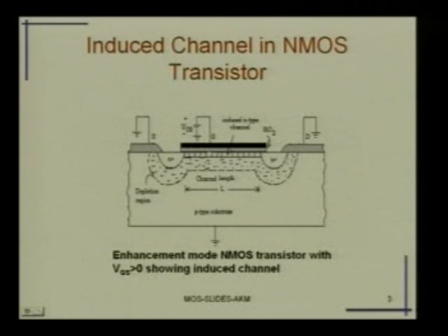So you move to the linear region, where linear characteristics will be established, although it is not exactly linear, but approximately you can say that it acts like a resistor. It becomes effectively a resistive element where current is flowing from the source to the drain. But the entire function will depend upon how much voltage you apply between gate and source. Now, to come back to what literally happens,